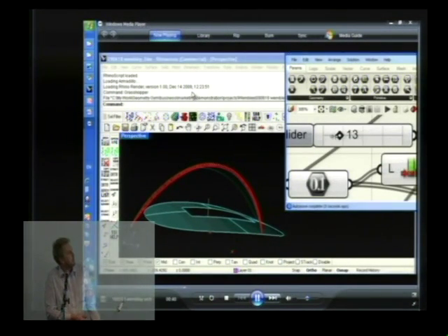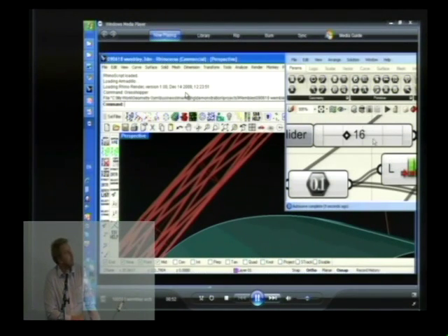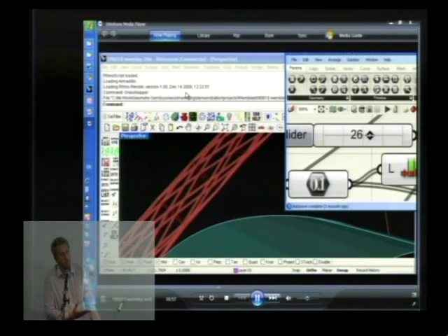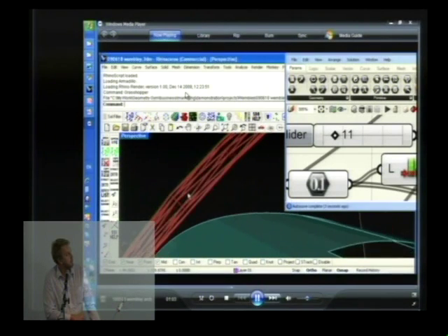Also the appearance of the arch, that in Grasshopper, if you set up so that it does the spiral lattice parametrically, you can use the sliders to control the number of spirals or lattice spirals. You can control how many division points, and really explore the design to come up with something aesthetically as well as functioning well structurally, to try and find the best solution.